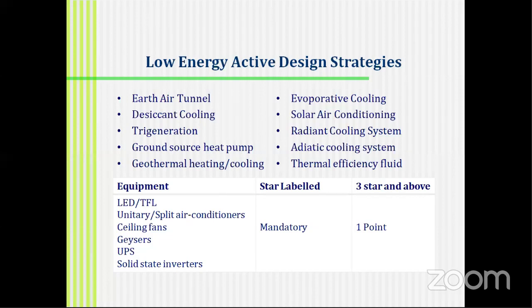This uses the property that 4 meters below ground, there is almost uniform temperature through the entire year. So that means if we can take our air 4 meters down and loop it through coils and then bring it up, more or less the cooling is done. The earth is doing the cooling for you. If this kind of efficiency can be integrated into our building design, we are trying to reduce the dependence on energy, which is generating so much of greenhouse gases and flue gases